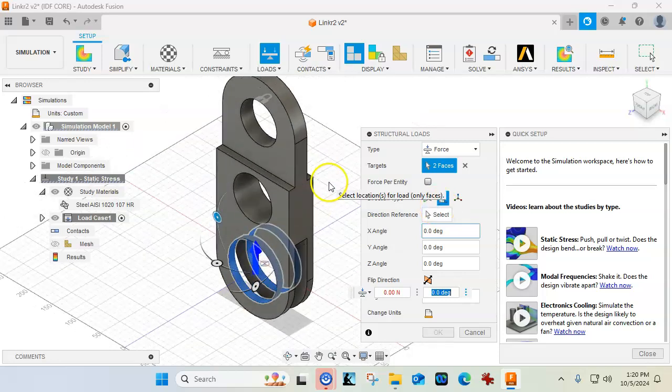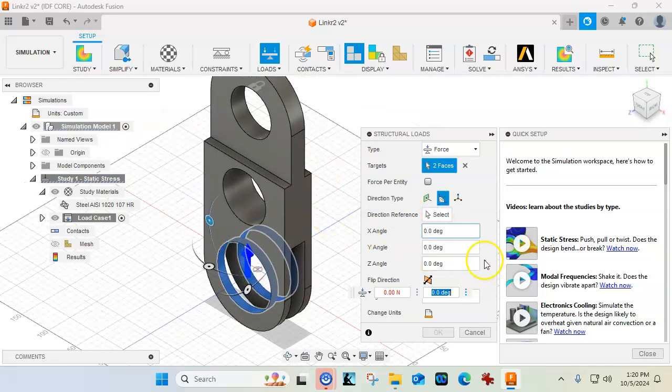So where is my orbit? So I can see the blue arrow is facing up, which would be more in the way of compression. So let's shift that to 180 so that it's pointed down, direction of gravity.